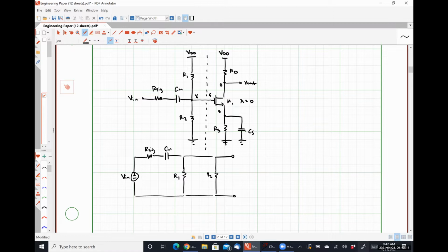And this node right here, where the capacitor and R1 and R2 are connected, is my node X in my original diagram. And down here is ground in my original diagram. And I could find a Thevenin equivalent voltage, which would be related in some way to our actual applied input voltage. So hopefully everybody can see that I can get here just using very simple voltage division.